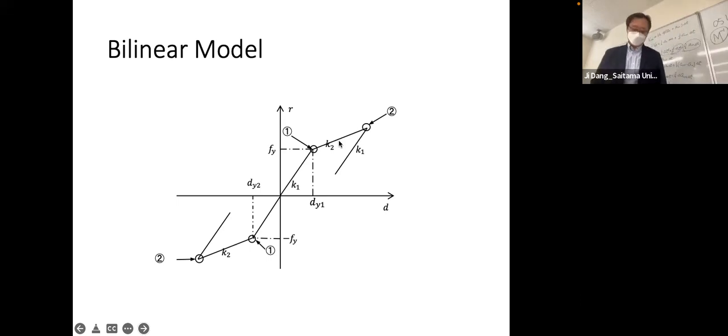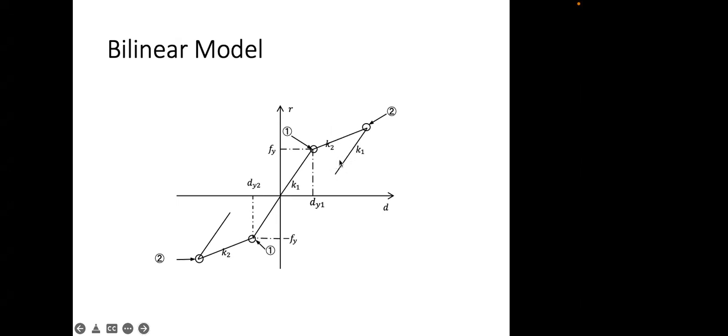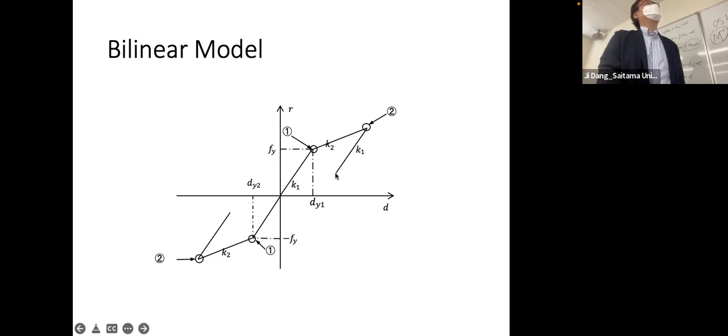static mechanics, but we didn't know what this kind of non-linearity, this kind of plastic loading, does to the dynamic effects, unless we do some experiment or simulation here. So theoretically, this kind of unloading will use the initial stiffness, as we also observed from a lot of experiments. So once they unload, they will keep the first stiffness until yield again.